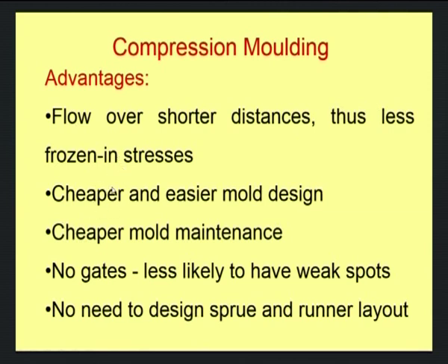And then looking into the cost, it is a cheaper and easier mold design, and maintenance is also very easy. Simply you have to remove the mold from the machine, and there are no gates required, unlike injection molding.